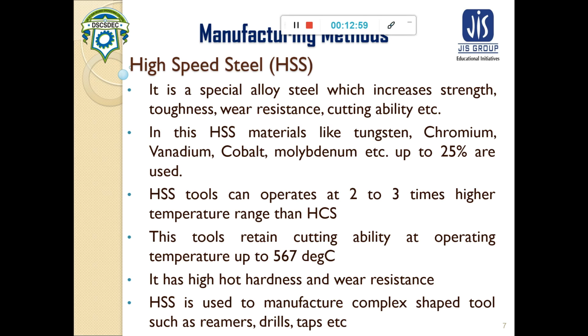The HSS tool retains its rated cutting ability up to a temperature of 567 degrees Celsius. And this HSS has high hot hardness and high wear resistance.